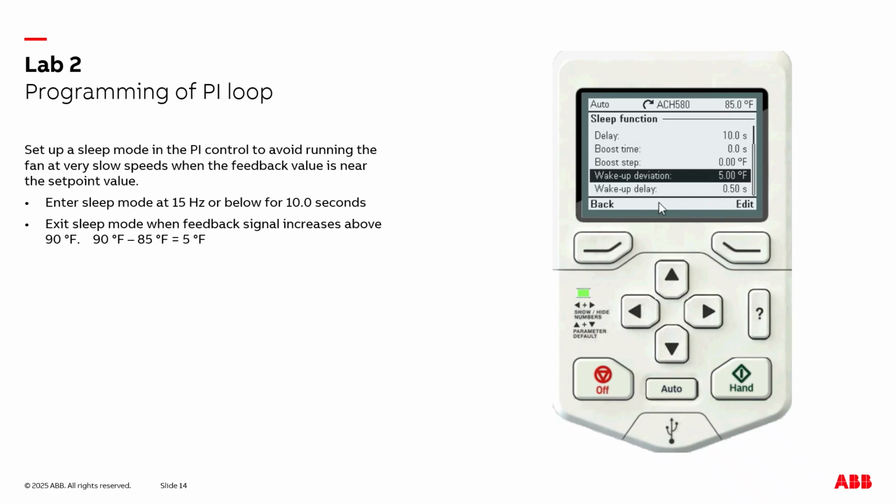And by default, we're not being asked to adjust this, but the wake up delay is half a second. This is kind of like the same concept of going into sleep mode. We waited 10 seconds. Here, we're going to delay half a second if we reach 90 degrees Fahrenheit before we start running the motor. And we're just going to leave that alone because we're not being asked to change that.